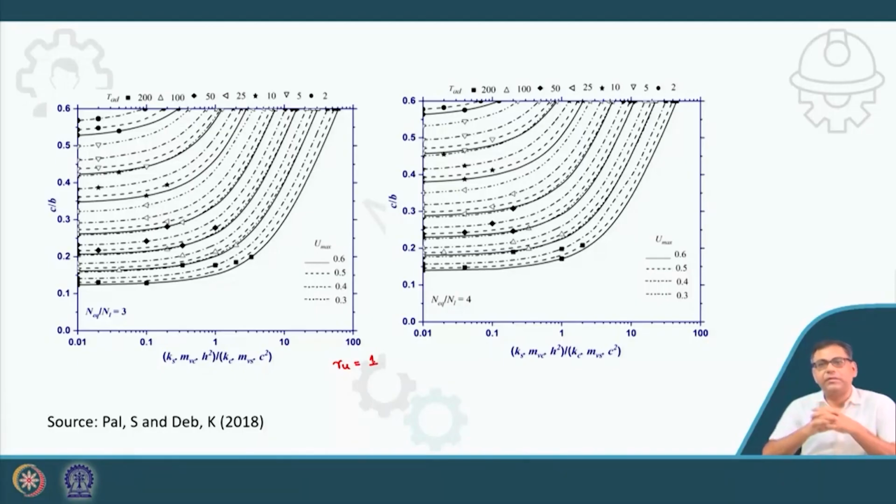It has also been observed that beyond this 0.6, as your RU value increases, your strength reduces, and the stone column, for its stability, needs the strength of the surrounding soil.